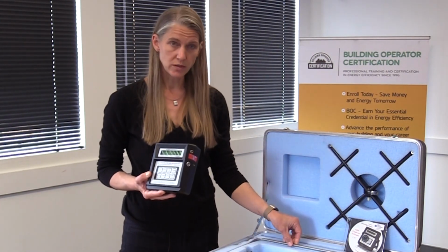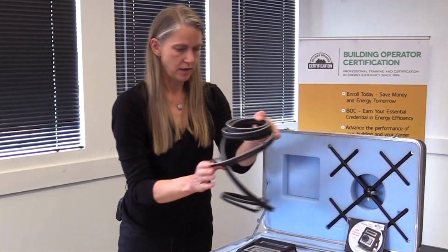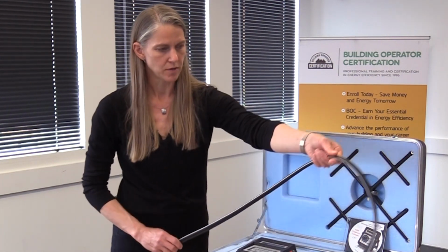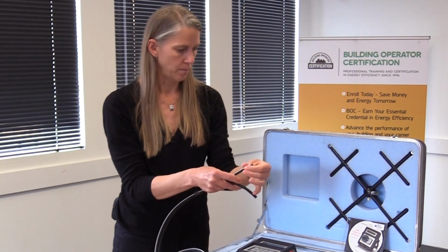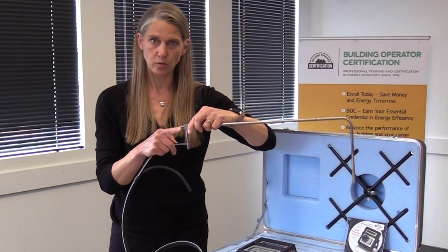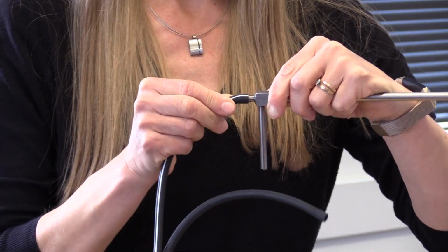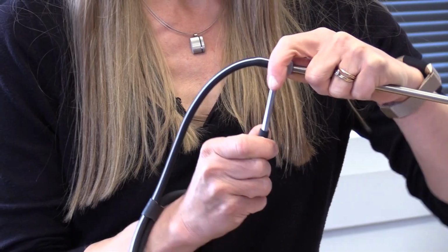So before we can use this and take our measurements, we have to connect and set up the meter for our use. The kit in here has these double hoses, and one of these hoses has a white stripe. We're going to use that to connect to the positive port. The positive port on the pitot tube is here at the top. So we connect that hose there, and the other, plain black hose will connect at the bottom at the negative.